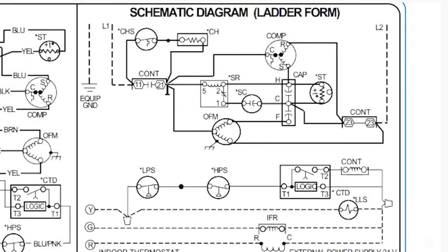Now you go through the compressor and you see the compressor common is connected to L1. L1 connected to the compressor common through the compressor contactor. The only way that this compressor can come on is if this switch goes from normally open to energized and closed, so the slash. So it has got to get the slash across it, the path across the switch for the electrons to travel through and hit the compressor.